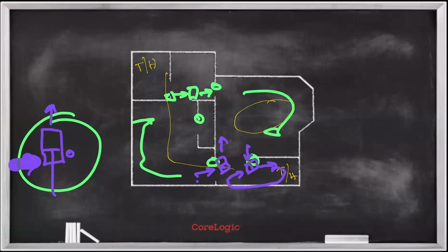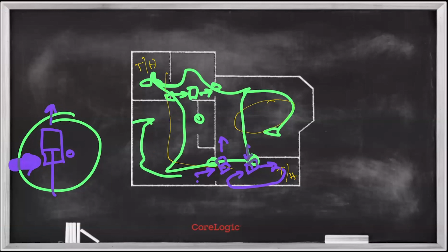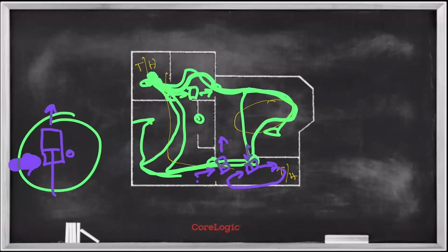Okay. Once you've established that, and every room has a mix with the next, you're going to have great circulation to the tune of 1,000 or more cubic feet per minute, because that's the CFM on these air movers, blending the air from one end of the chamber to the other. If you were to become a little water molecule and travel along this train all the way along the space, based on the speed of this air movement, it would probably take you about 3 or 4 seconds at the most to make a whole revolution around that entire space. So it's a very, very rapid exchange between two rooms.